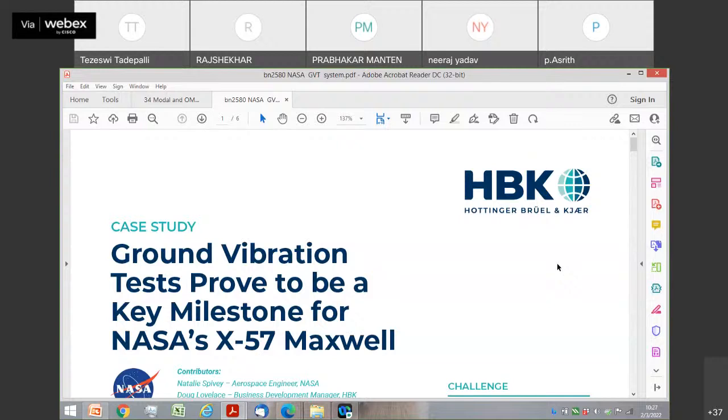I will try to show you an example of that software after this. But this is a very common technique used, and in fact, this has been used even in HAL for the missile launches from the aircraft to measure what will be the shock of the aircraft when the missile is launched from the aircraft or when the missile hits the aircraft. You have a software which can pick up this time domain and then do an SRS calculation of about 37 different parameters immediately.